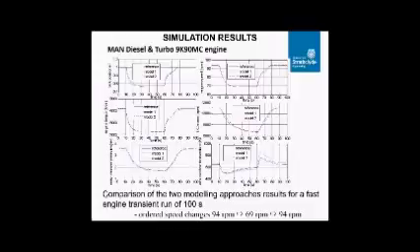The second approach, as I said before, is where the engine receivers are modeled as open thermodynamic systems. This is attributed to the detailed modeling of the engine receivers. Adequate agreement in the prediction of engine parameters, except for the exhaust receiver temperature, is also obtained using the first approach. The first approach is when no mass accumulation is considered between the engine components.